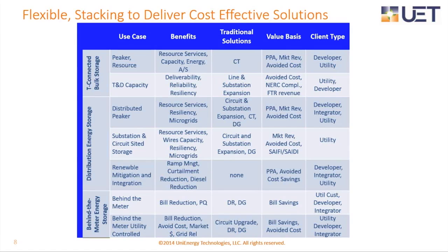At this level, I'm also seeing a lot of renewable integration in the 500 kilowatt to 5 megawatt range: PV ramp management, curtailment mitigation, and that's the strongest energy arbitrage play, when you have otherwise not delivered renewable generation that you can capture with the battery and then return it later. And again, to do that well, you need some energy, and that's when flow batteries really come to the fore